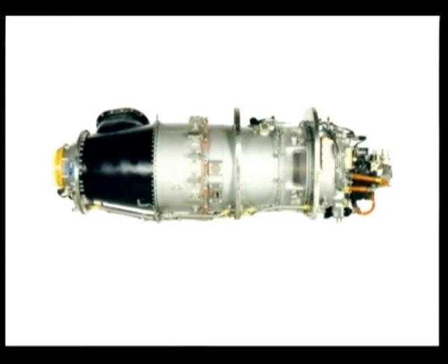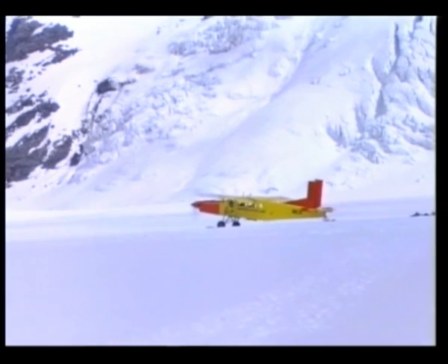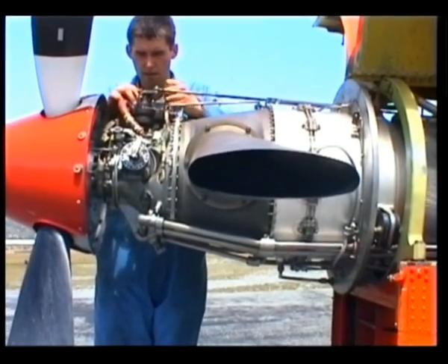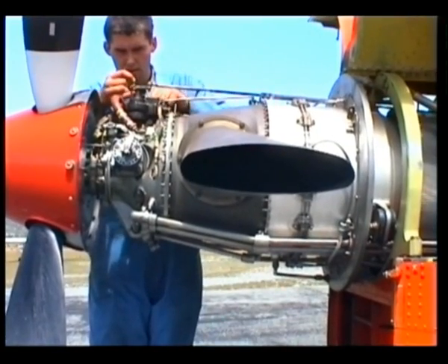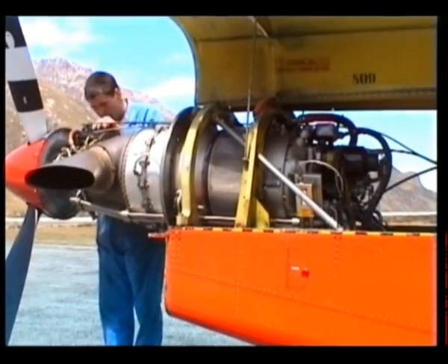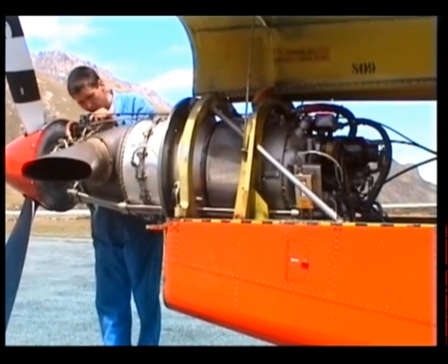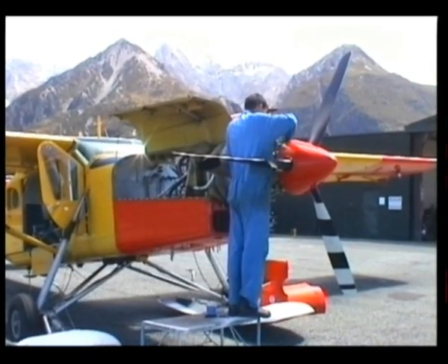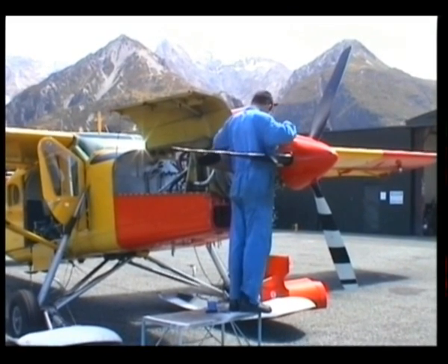For example, the ubiquitous PT6, which has undergone a number of changes in its long life, has 3 or 4 stage axial, plus centrifugal compressors, an annular combustor, a single stage compressor turbine, and a single stage power turbine. The engine can rate between 500 to 1,650 horsepower. These are details that will be covered within a type rating course, but they serve to illustrate the combinative nature of the modern gas turbine engine.